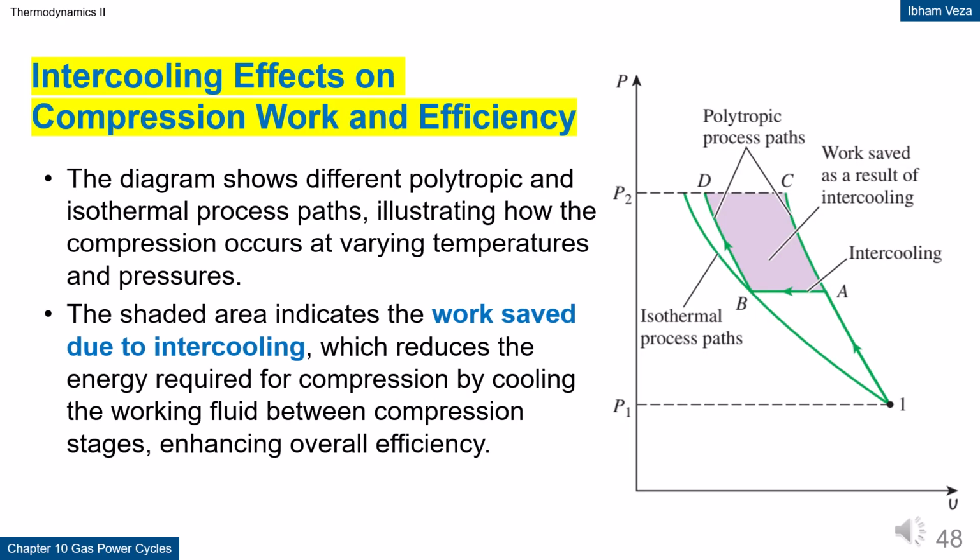Intercooling effects on compression work and efficiency. This figure shows that cooling between compression stages can reduce the compressor work. By lowering the fluid temperature before the next compression stage, the required work becomes smaller. The shaded area in the diagram indicates the work saved due to intercooling.